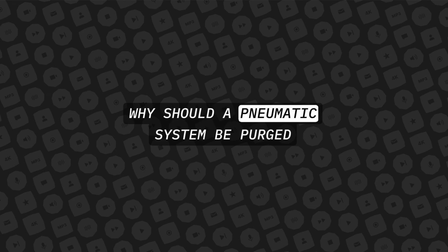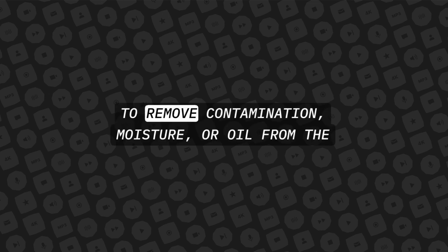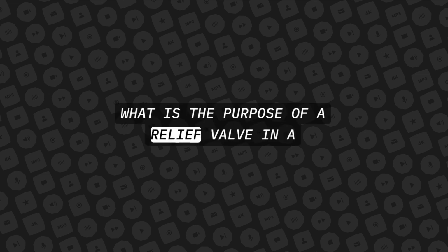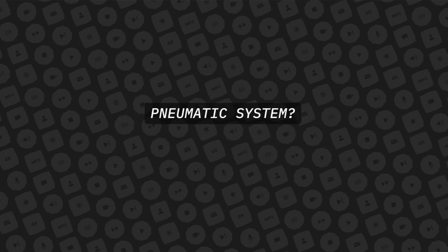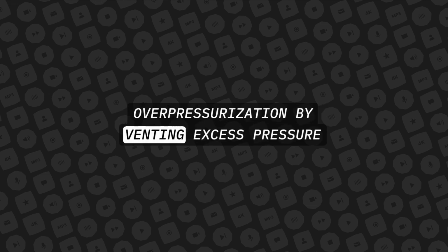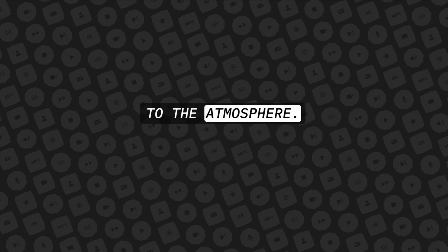Why should a pneumatic system be purged periodically? To remove contamination, moisture, or oil from the components and lines. What is the purpose of a relief valve in a pneumatic system? The relief valve protects the system against overpressurization by venting excess pressure to the atmosphere.